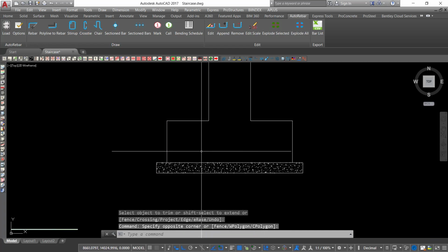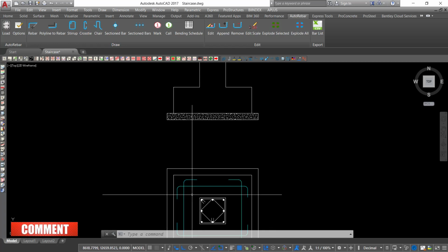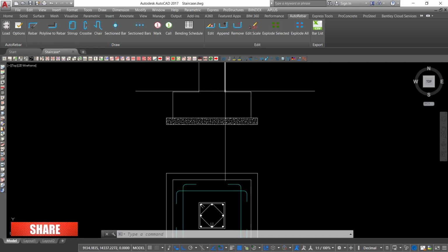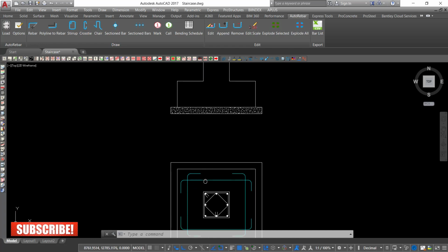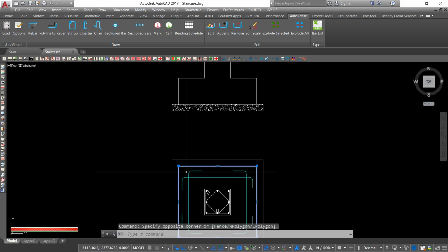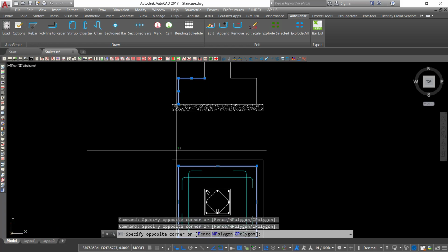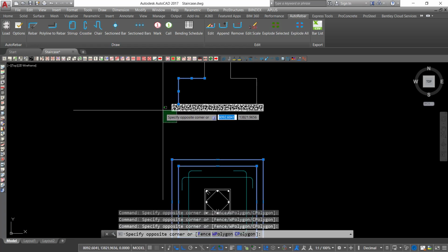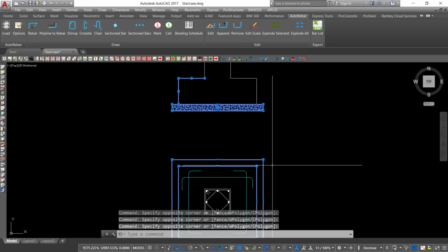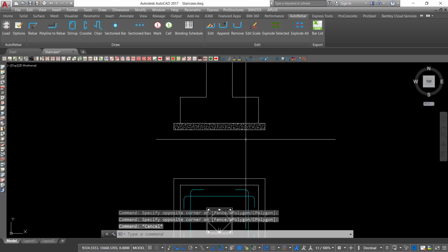So let's begin first of all by laying our rebars. The bars you're seeing at the bottom end here, we can now see them on the elevation here because this column base is this one, and this one here is the blinding you're seeing here. So this is the elevation of this. Let's escape and start laying our rebar at the column base.